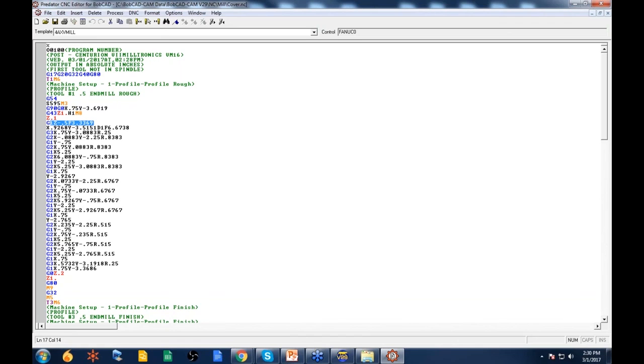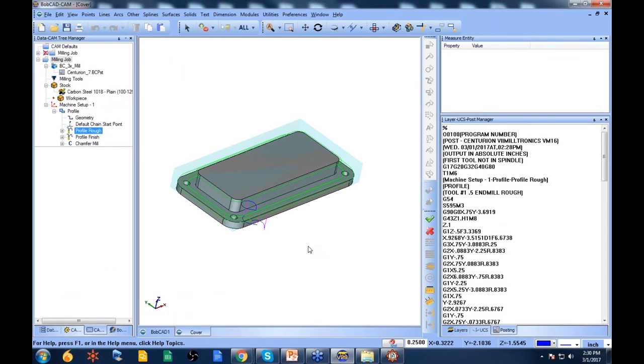Steve has a question. Do you use M codes to drive a plasma torch? And how do you do it? Steve, the M codes are really just to turn the plasma on and plasma off. That's the main purpose of them. Depending on which brand you have, you may not even need that. Generally, like an ESAB or a Mach 3, or what's one of the other ones I'm thinking of? There's a bunch that are out there, but they're actually really easy to set up.